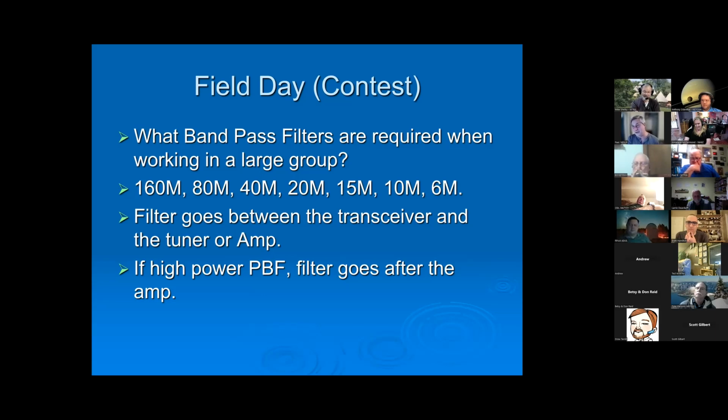You can't use the internal tuner in the process of trying to do this. It's not physically impossible to open up the radio and stick the bandpass filter between it and the internal tuner. So please, if you're planning on coming to Field Day or 7QP, make sure you have an external tuner so that you can put the bandpass filter between the two. Very good point. That's something I didn't think about adding in here. But yeah, having that bandpass filter on the outbound side of your tuner will end up scrambling the eggs. It won't work right.